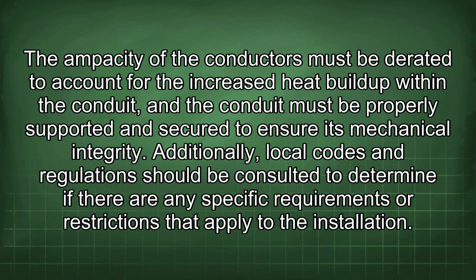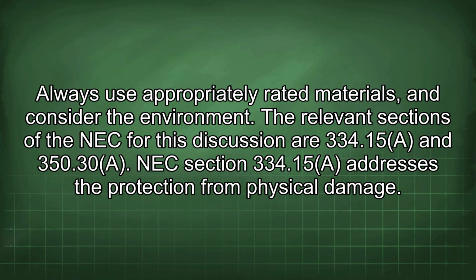Additionally, local codes and regulations should be consulted to determine if there are any specific requirements or restrictions that apply to the installation. Always use appropriately rated materials and consider the environment. The relevant sections of the NEC for this discussion are 334.15a and 350.30a.